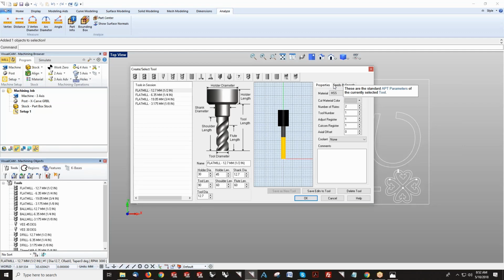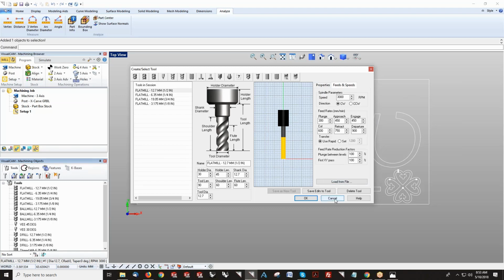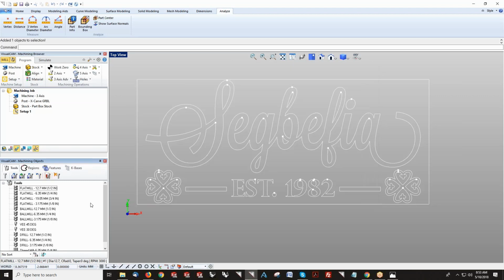We do not have a catalog of tools where you can just put in the item number to fill in the properties. But from the place where you source your tools, they will have some recommendations on what you can go with for spindle speed and RPM based on the material you're working with, and you can actually just put this in here and then save those tools to your library, so the next time you select a tool, it'll automatically have that information in there.